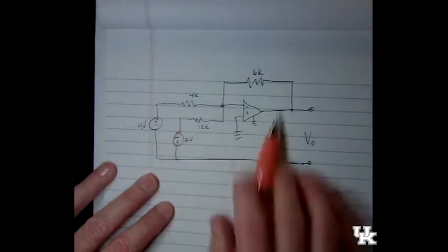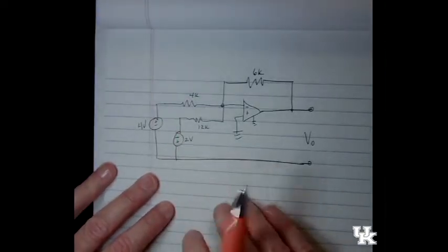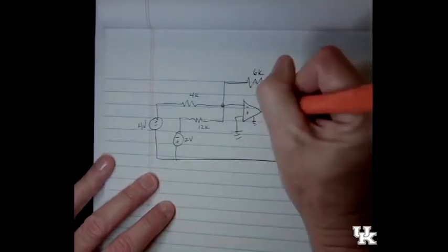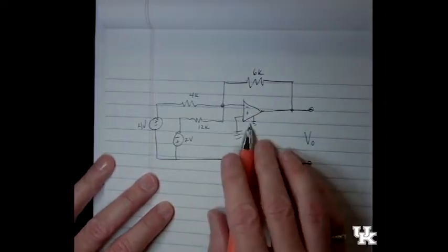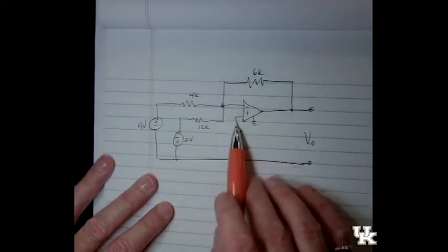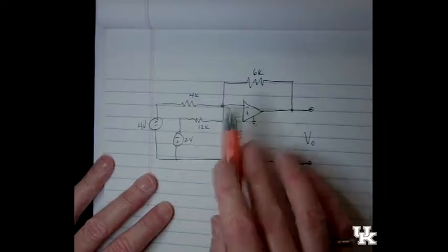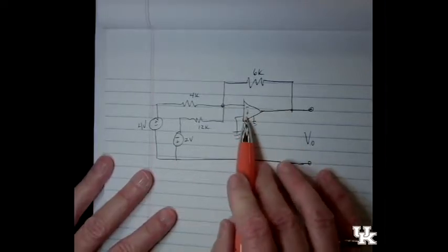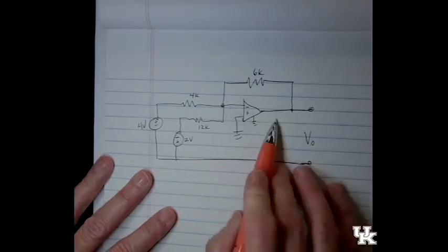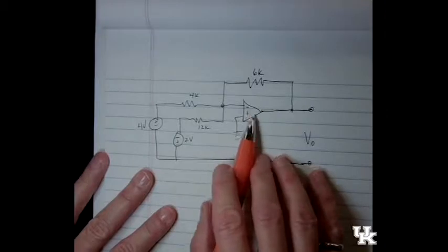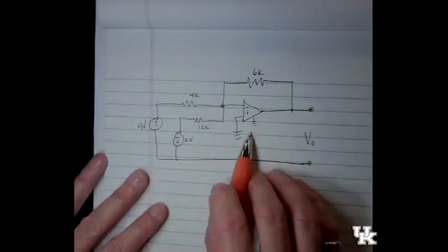I picked out an OPAmp problem to work on, just to give me a chance to go over it with you. So the OPAmp symbol here, we usually draw at a minimum 3 connections: the inverting at the minus, the non-inverting, and the output. So those 3 voltages, those node voltages. And there are 2 other connections that we don't always mark, but we sort of assume that they're there.